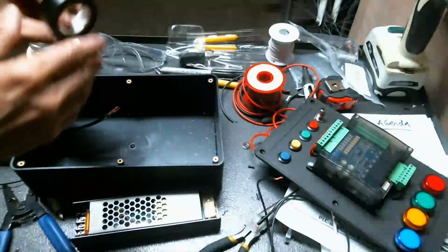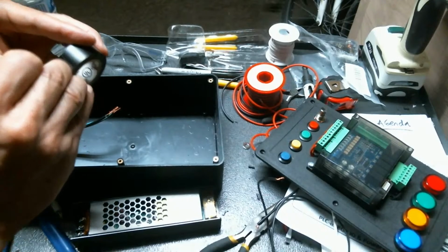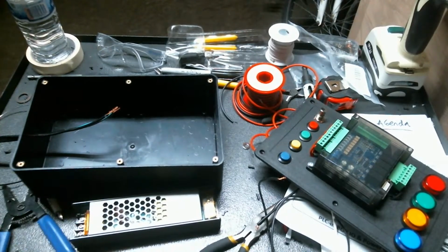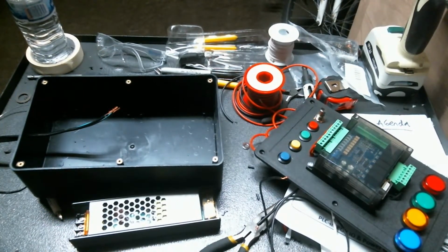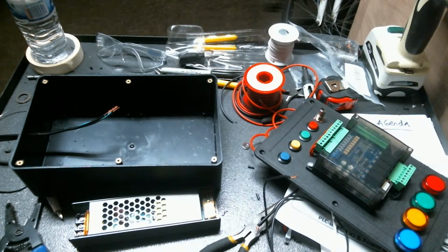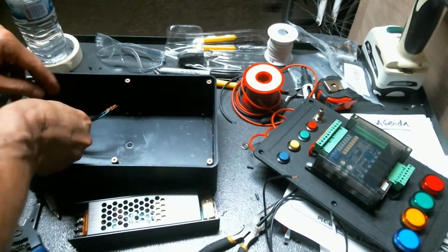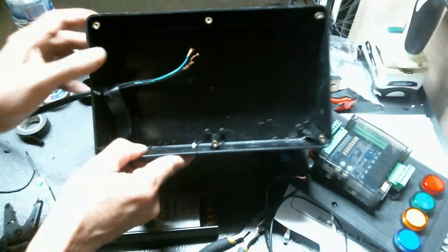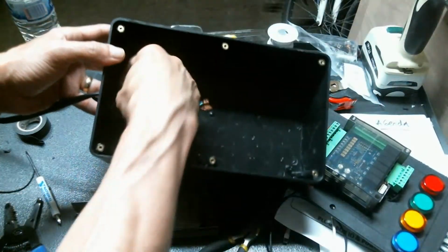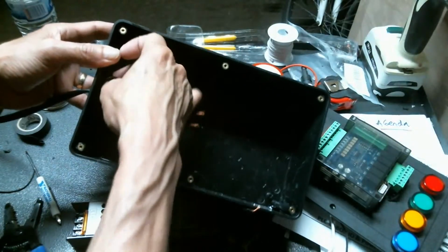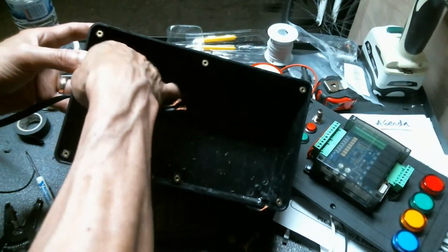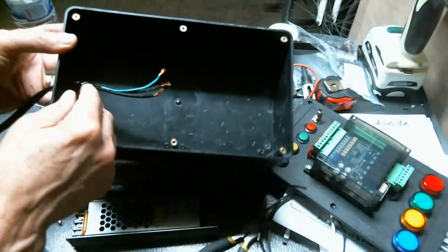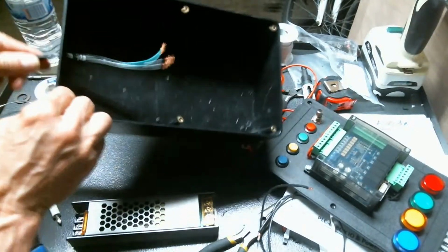And what you want to do is something very practical here. In case someone pulls this out, you're going to put some tape around. They actually sell some little plastic rubber pieces for this, but I found that if I just tape around like that, right? I'm taping. If you can see, I'm putting a tape around here. That's going to be enough to hold the wire in place in case somebody pulls that. If you want to go fancy, you can find a rubber retainer that goes in here. But you see that? That's pretty good.